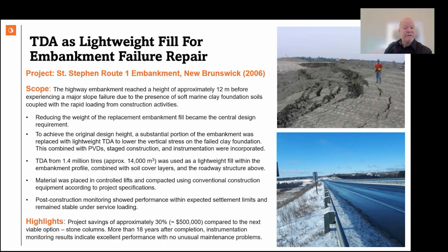This project was the first TDA project in Atlantic Canada and the largest TDA project in Canada at the time. And at the time, it was the second largest in North America. We used 1.4 million end-of-use tires to construct this project. This project is an especially important case study in the industry because it's been monitored and continues to be monitored after 19 years. And the embankment, the highway, continues to perform to this day.